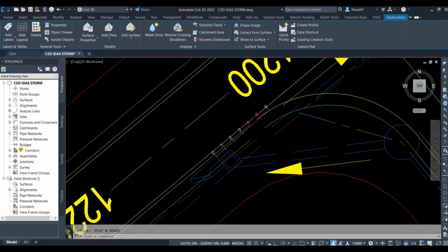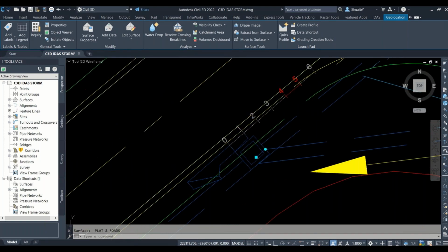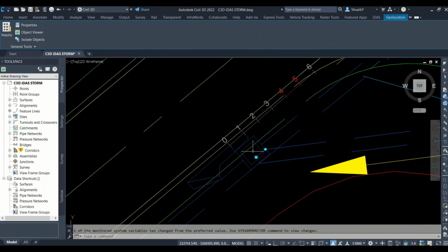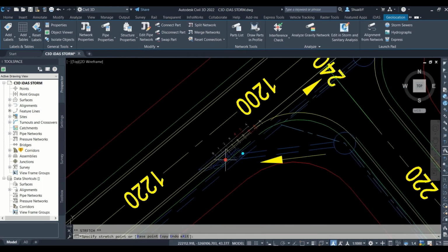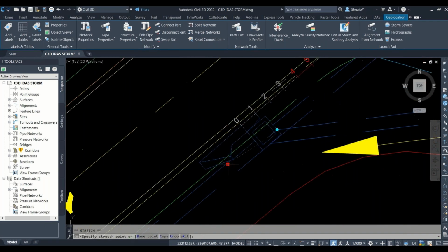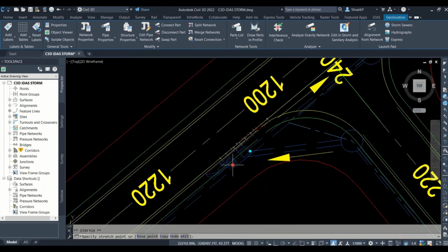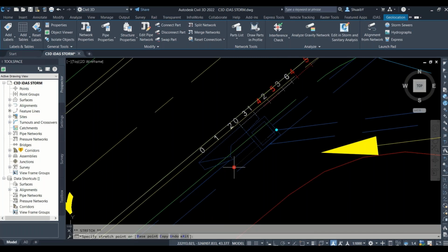And you can see I can now just simply align this to the edge of travelway or the edge of the lane. I could use the square grip to move that towards it, like you will see now. So I'll select that. I will move the entire element to the position. So I'll just position it quite roughly right now. Okay, and I can also use the circular grip to rotate it. Okay, so you will just need to fiddle around a little bit here.